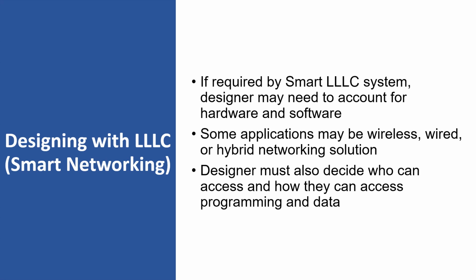If required by a smart luminaire-level lighting control system, the designer may need to incorporate the networking hardware, hub, gateway, server, and software into the project deliverables. Some applications can be served by wireless networking, wired networking, or a hybrid wired-wireless solution. The designer must also decide how programming and data will be accessed, web browser, mobile app, and who will be allowed to access it.